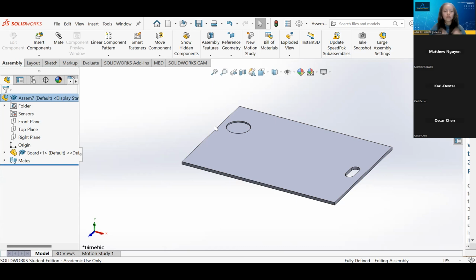Great question. Float just releases all the constraints that your part has. So float means, how do I put it? Imagine a body of water. And imagine your part is anchored, right? The anchor is to the bottom of the floor. It doesn't move. But if I say I want this part to float, I'm essentially releasing it from the anchor, and now it's just floating wherever it is. It's in an arbitrary point of space.